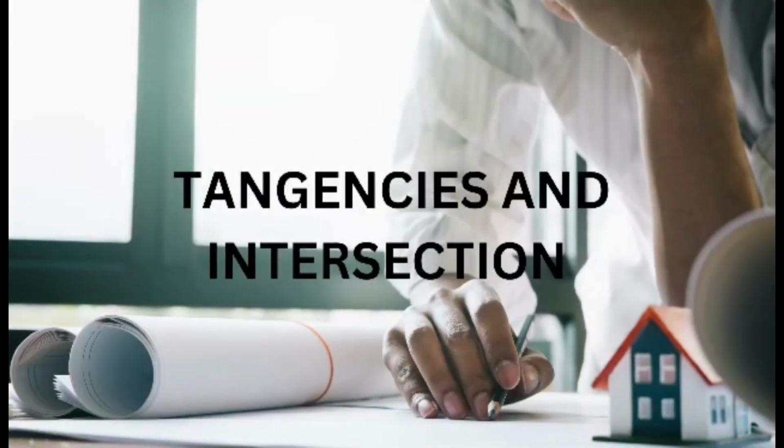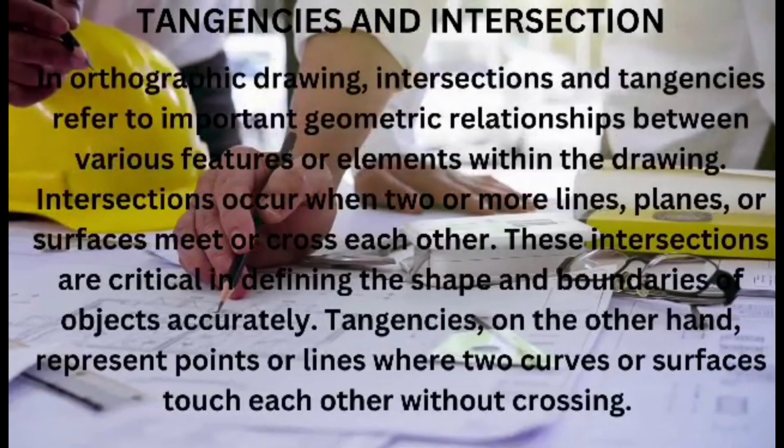Tangencies and intersections. In orthographic drawing, intersections and tangencies refer to important geometric relationships between various features or elements within the drawing. Intersections occur when two or more lines, planes, or surfaces meet or cross each other. These intersections are critical in defining the shape and boundaries of objects. Tangencies, on the other hand, represent points or lines where two curves or surfaces touch each other without crossing. Tangent points are commonly found in circles or arcs that smoothly transition into other shapes or surfaces, ensuring seamless and continuous visual representation in the drawing.